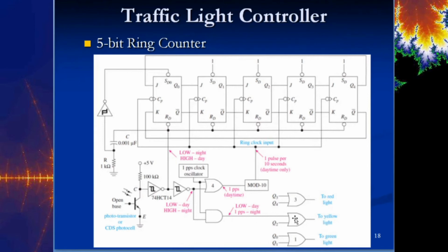So this yellow light is going to blink. So there must be, it says a photo transistor or a photocell. It's going to operate until there's no light. When there's no light, that part of the circuit drops out, and essentially what you have here is this 1 pulse per second clock oscillator is going to blink this yellow light. Okay, so kind of a cool operation there.